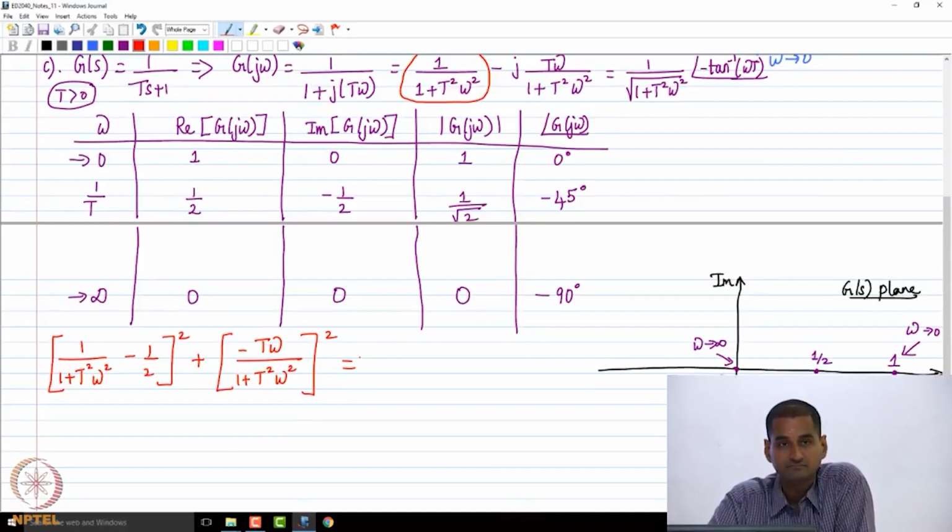Yeah. Here the imaginary part is minus t omega times the real part, right? So, if you are plotting imaginary part versus real part, it will just be a set of lines with slope minus t omega, and as omega keeps varying, the slope keeps changing. Please note that the real part and the imaginary part are parameterized with respect to omega. So what you are saying is correct if I plot for a particular omega and vary the real part, but it does not work like that.